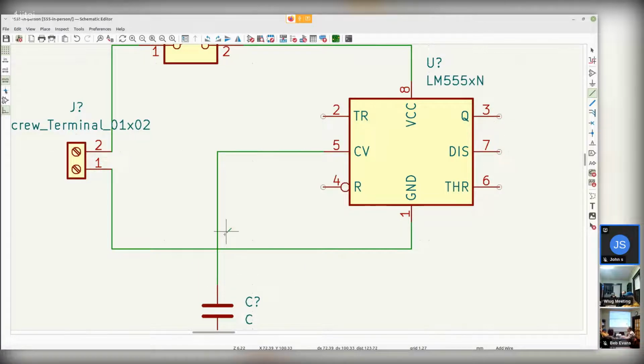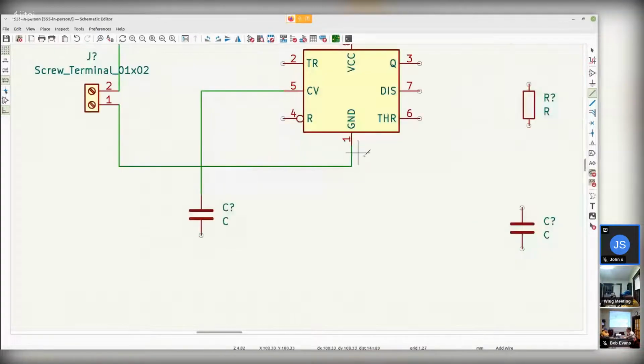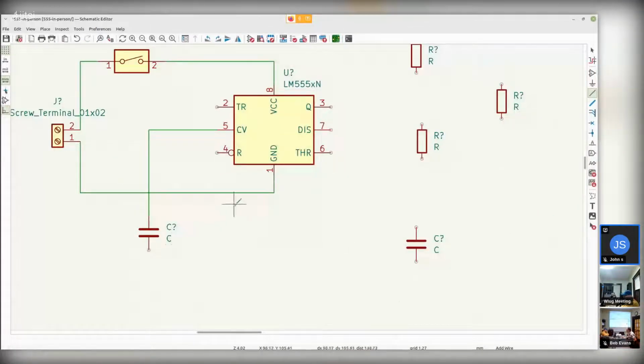And so when you have wires that cross like this, you can see this in the center a little bit over here. So when the wires are crossing, unless there's a green dot there, that means they're physically crossing. If there's a dot there, then it means they're intersecting. Okay. And I'll show you one of those in just a second. Yeah. The dot shows there's a connection.